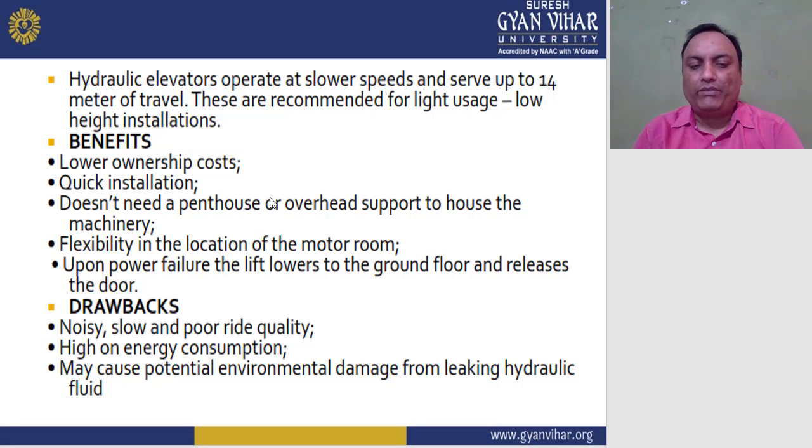So this is the benefit of this lift, and this lift cannot get stuck at any place, right? The drawbacks are that it is very noisy, slow, with poor ride quality, high energy consumption, and may cause potential environmental damage from leakage of hydraulic fluid, right?